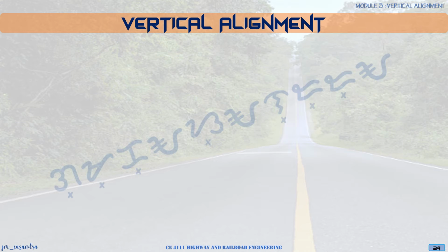heights of less than 0.6 meters for our sight or stopping sight distance calculations would usually result in longer crest vertical curves without a documented decrease in the frequency or severity of the crashes.